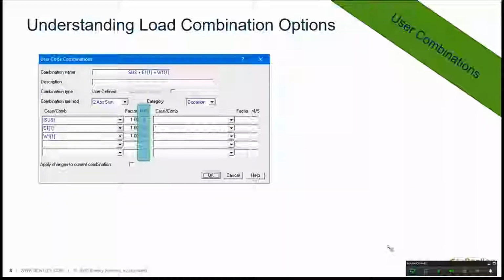In general, basic load cases such as gravity, temperature, pressure, etc., can be only combined at the moment force level. Load combinations can be combined at either the moment force level or the stress level, and results from predefined stress categories can be combined only at the stress level. For combinations that are calculated in the von Mises or the tensile stress categories, the results can be combined only at the moment force level.